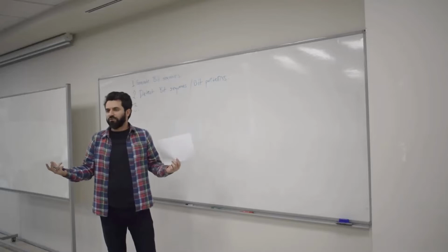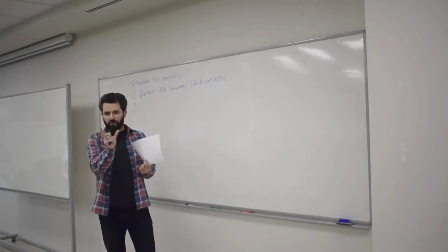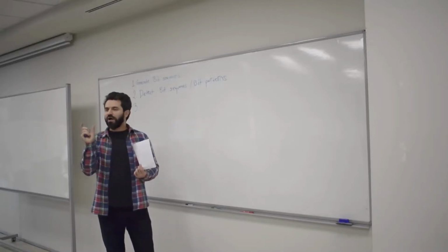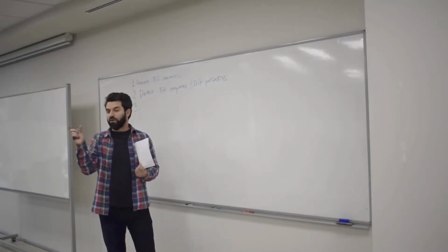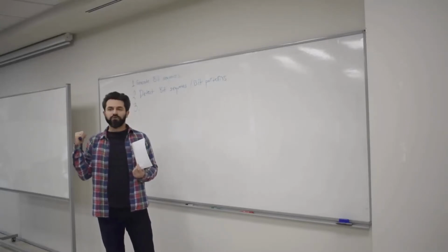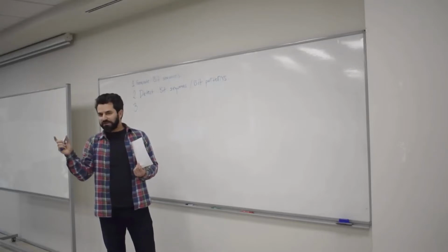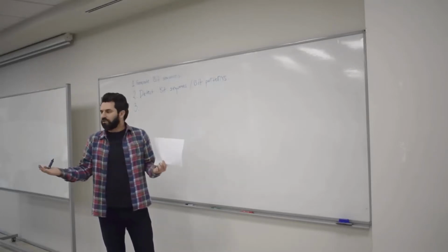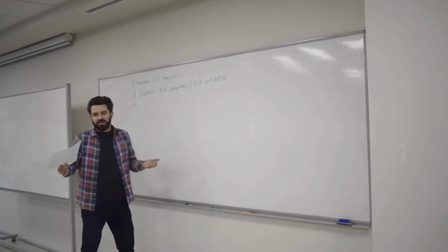You basically have a window of 4 bits long, and then you move that window over your sequence. When you have a specific sequence that you want, for instance, 1, 0, 1, 1, then you output a 1. If you don't detect any specific sequence, such as 1, 0, 1, 1, then you output a 0. That's a sequence detector, for example.